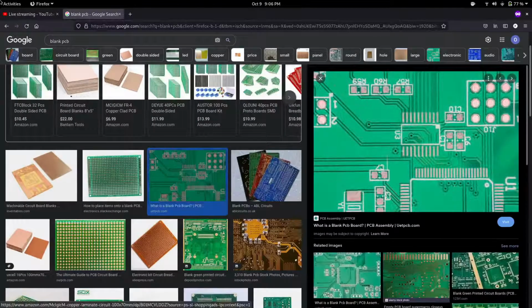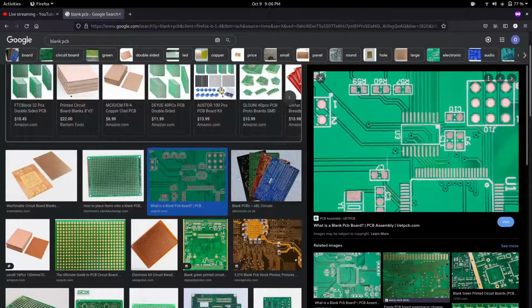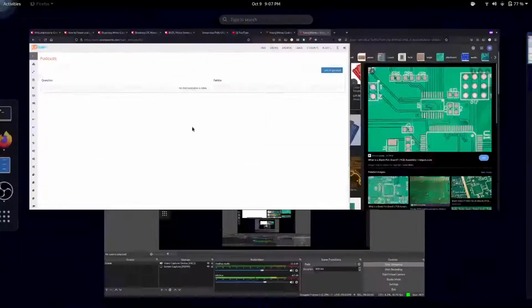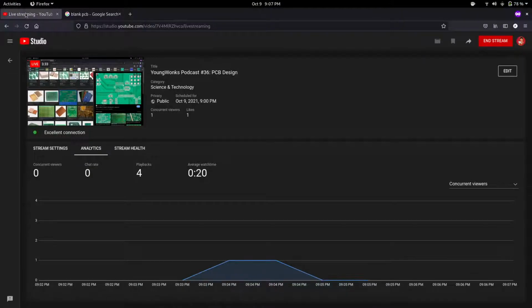Also, if you get into the really complicated stuff, printed circuit boards actually can have antennas built into them, and they can have inductance or capacitance just in the traces. Because you are able to make any shape out of the copper on the board that you want, you can actually create an antenna, because an antenna is just a wire of a certain shape, right? So there's a lot of more advanced topics in PCB design that relate to actually using the PCB itself to accomplish some goal. Or if you've got really fast signals where the actual length of the trace that a signal is transmitted through matters, you might find that it's important to...